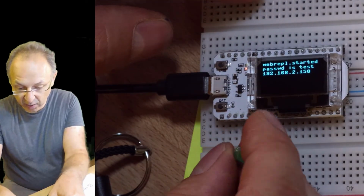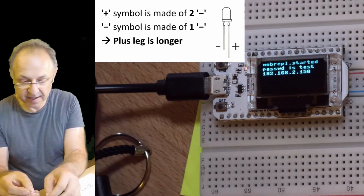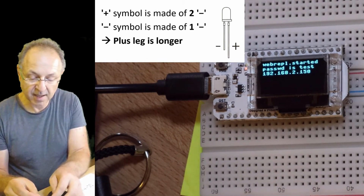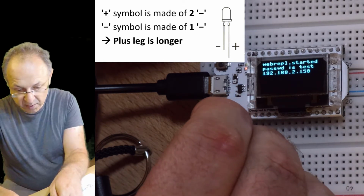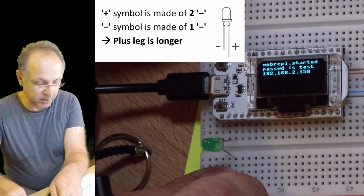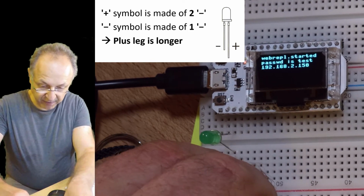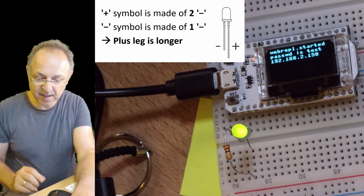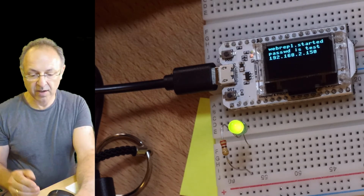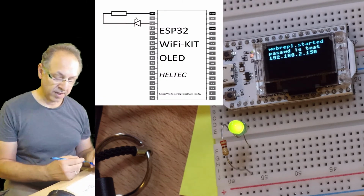So what I do is I connect it with the long side, which is the plus, and it's easy to remember: long plus has two dashes, minus has one dash, so the long side is plus. I connect this to 3.3 volts. The other side I put into an open field, and I connect that open field, which I have here, with ground. And what we see is our LED is constantly on. I just connected the LED, and basically this is the circuit we're seeing.